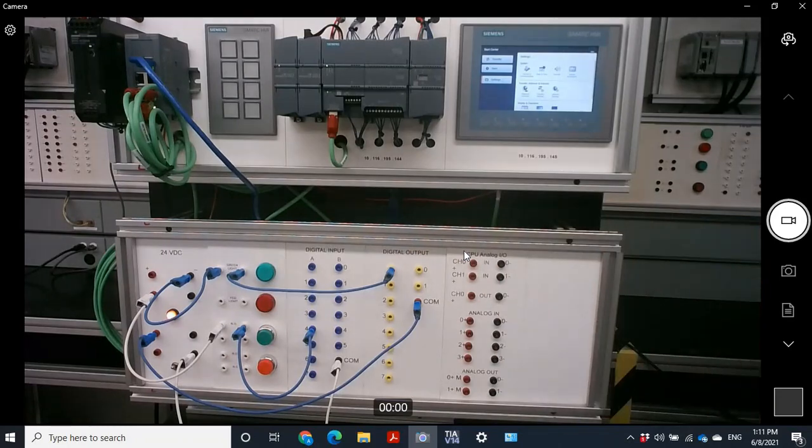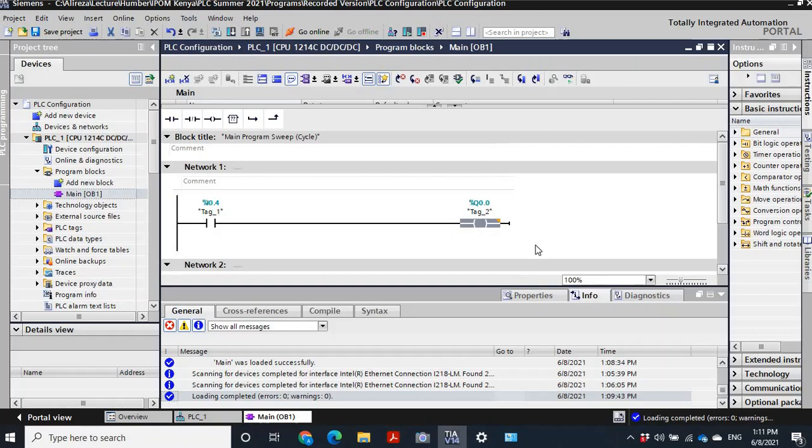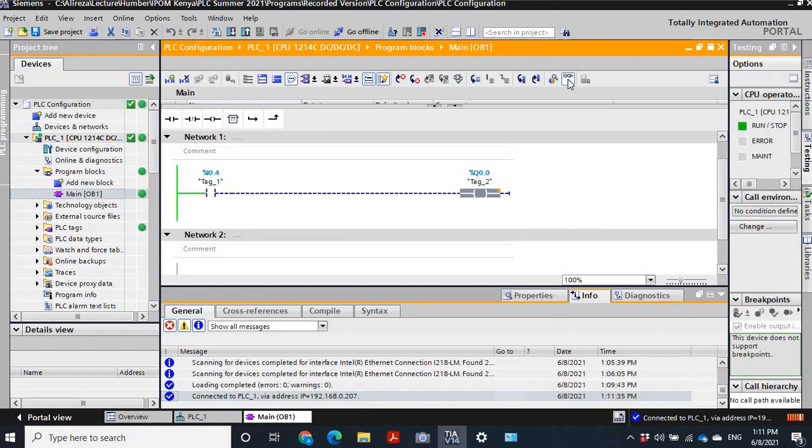To look at that in more detail, in the software there's an option that you can see the state of the variables in the PLC on your PC. So the states of the variables, inputs, outputs, or any other variables in the PLC, you can monitor them in the software on your PC. How? Here you have an icon, monitoring on off. This is the monitoring option. Click on this monitoring option, let's say enable that or turn it on. By default it is off.